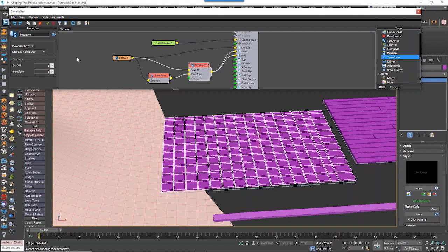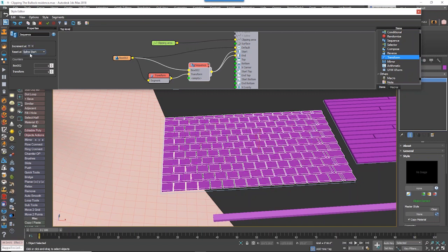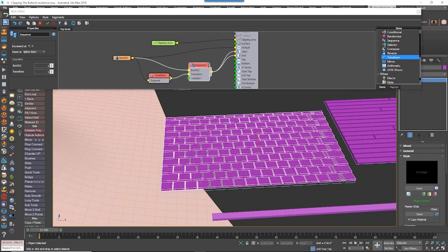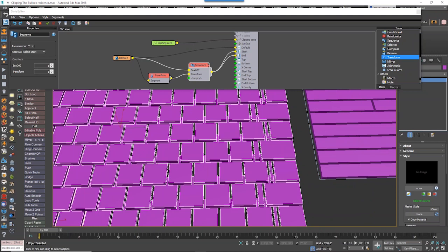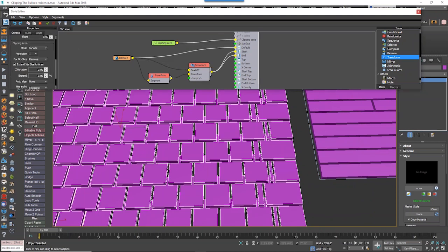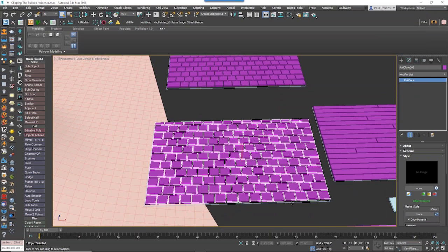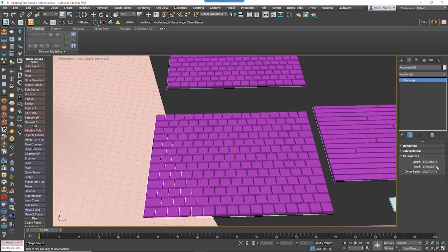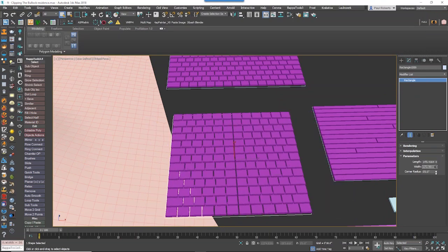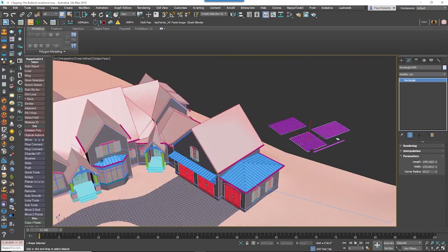Now it's only at the end, but what I need to do is to change the increment at value to y. That way the pattern goes up on the y-axis of the array instead of the x-axis. And the other thing I need to do, we talked about the distribution modes, the default modes earlier. It's set to tile at the moment, which means the last one is being sliced. If we set it to adaptive, you can see it fits together perfectly, like so.